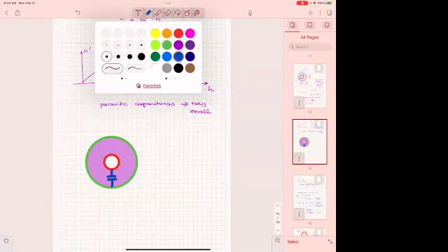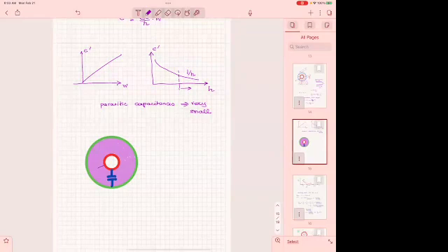So here, for example, we have found that all of them here per unit length, you have some kind of capacitance all around, and eventually the total of these, all of them are in parallel, are all capacitances that are created. So totally you have a capacitance per unit length, which is in farads per unit length, say per meter, all right? And that is the capacitance for this infinitely long line.